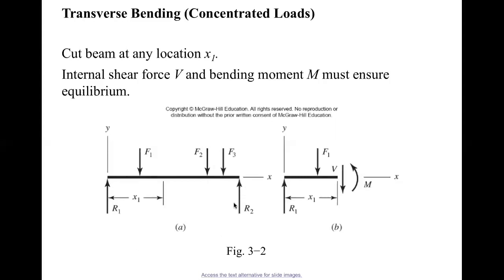So based on the moment equation about the origin, we can find R2, and then we can use the force balance in the y direction and find out R1. So I just described how to find the reaction forces R1, R2 based on statics. Again, as I said, if you forget statics, it's fine. But you should be able to remember forever how to write the force balance equation and the moment balance equation.